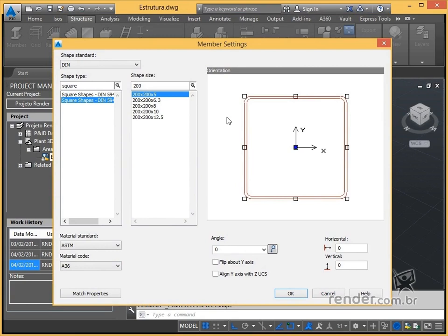After the basic profile information has been configured, we can align it with the lines of the grid. To the right of the dialog box, we can see a preview of the profile with the main nodes, which are the sides, corners and middle nodes, which we use to align. For this, we select the desired node. When you select an alignment node, the offset values are updated at the bottom of the preview. These values can be modified by the user so that the alignment point is different from the existing ones.